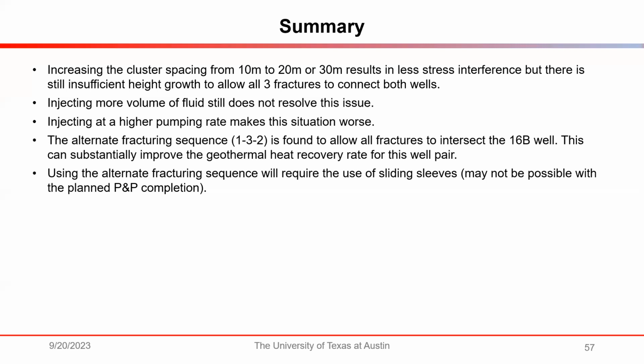You're not looking at that, and also the fractures we had in our models were much larger than the ones that you have. I mean, we had natural fractures going up to 100-meter radius, as sort of these circular fractures. And I would think if you hit an inclined, very large feature like that, you definitely would see some interaction in a slick water treatment with a propagating fracture. So it might be interesting to try adding even just a few larger, and if you have the capacity to have some inclined features, just match the actual 3D orientation of the sets we found, not just their azimuth.